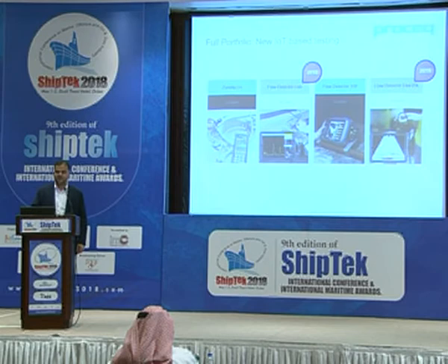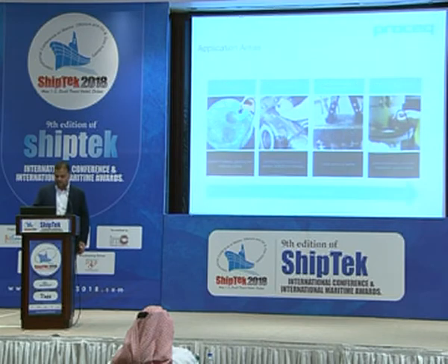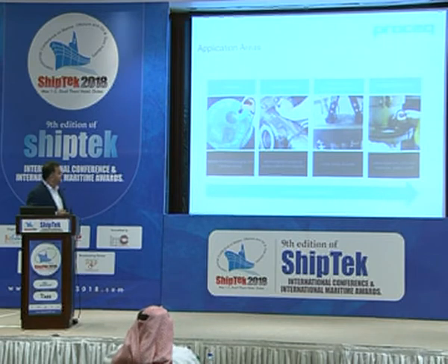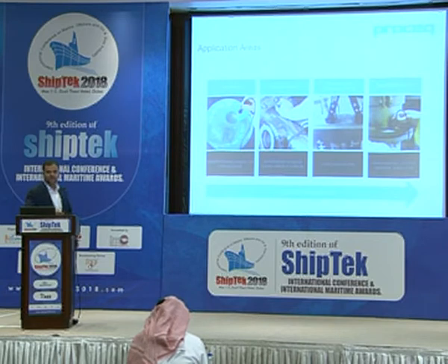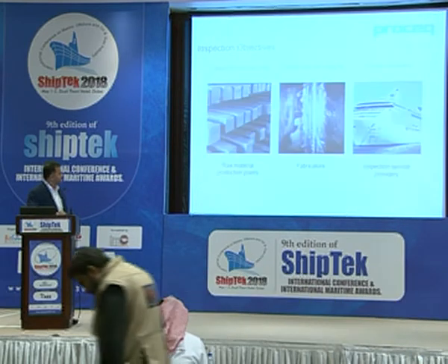That's in the pipeline. If you just have a quick look at the application areas, basically we are talking about thickness profiling, we are talking about the conventional UT, we are talking about the time of flight diffraction, which is TOFD, and the phased arrays. These are the common tests that are done in the shipping and marine industry as well as in the oil and gas industry.